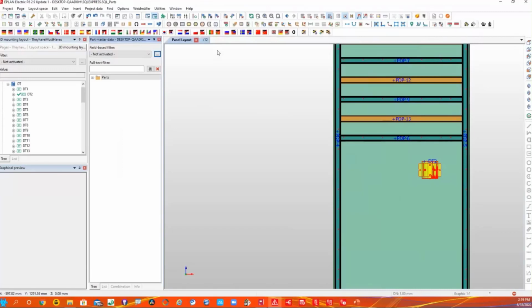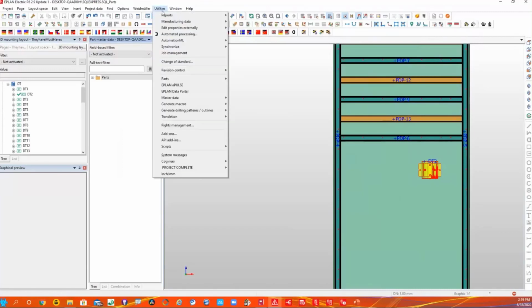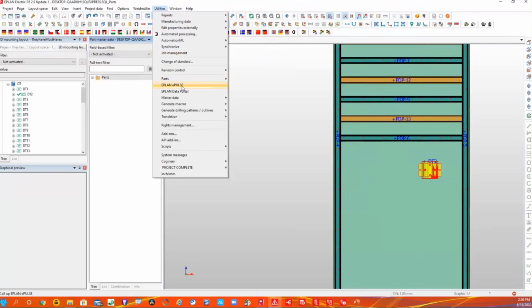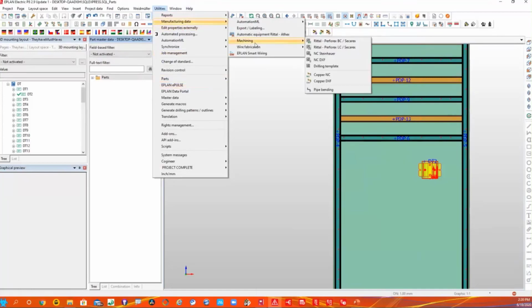There's tons. I mean, we can actually grab that information from the ProPanel space, since we have that detailed information that has been classified or identified by a procedure called E-class. Well, it's much more of a standard or a format, if you will, that is globally known. E-class allows the manufacturer to have a high level of detail, like cavity size, wire direction, and heat dissipation information. This benefits the user when they're using ProPanel to be able to export this information to different machine types.